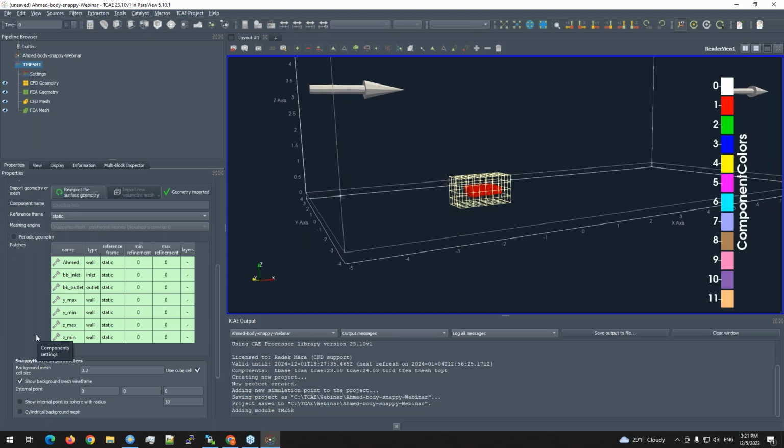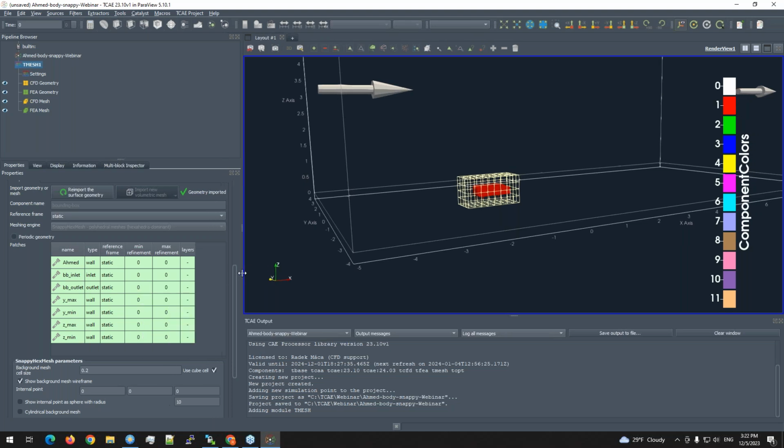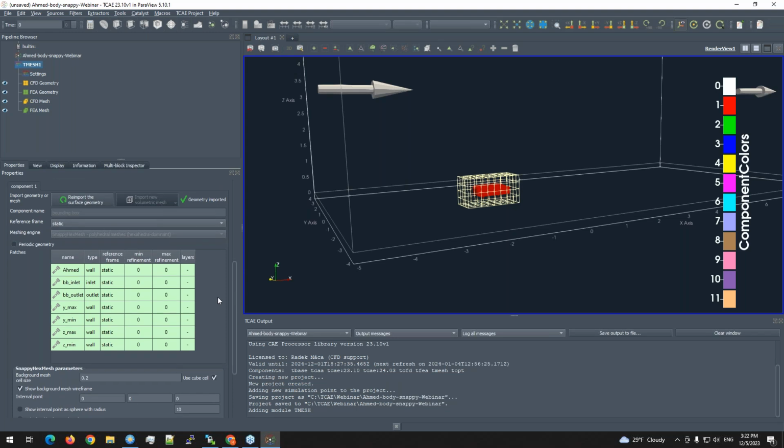Just to have the simulation quick, I will set it in a very rough way. I will set some rough mesh parameters to properly describe the object, but we can't expect very high accuracy of the results, because the accuracy depends on the mesh refinement, of course. But to save some time and to run it live, I will set it in some rough way.